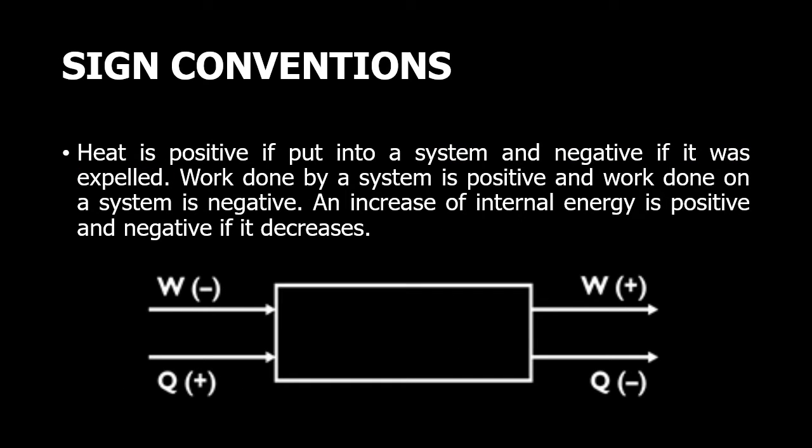But how do we follow sign conventions in problems involving thermodynamics? So remember this: heat is positive if it is put into a system, and negative if it is expelled. On the other hand, work done by a system is positive and work done on a system is negative. An increase of internal energy is positive and negative if it decreases. So remember that.